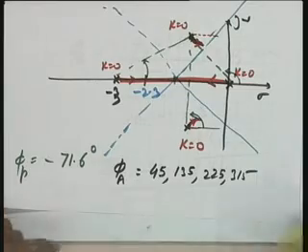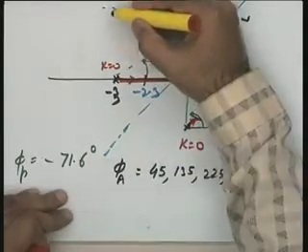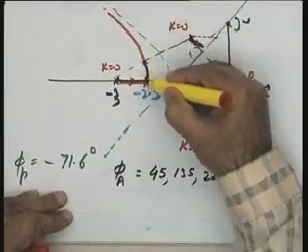This concept will follow in the examination also. Please see, I will not worry about the very exact values. I will worry about the logical sequence you have followed as far as the analysis or design problem is concerned. So in this particular case, for example, you find minus 2.3 appears over here. This is the breakaway point, and hence logically the root locus branches will go this way.